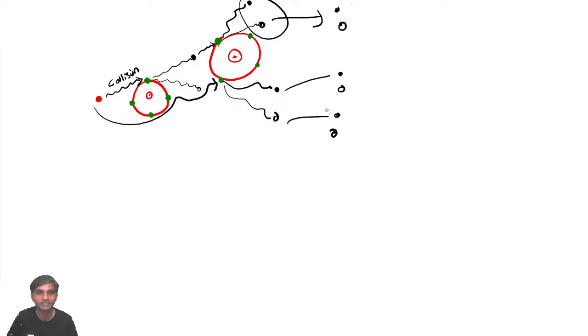So now what's happening, sir? Slowly the number is multiplying. It is slowly increasing. As the temperature increases, this free electron which has come is colliding with the electrons present in the covalent bonds, and this will again make an electron-hole pair. So this electron-hole pair will again multiply.